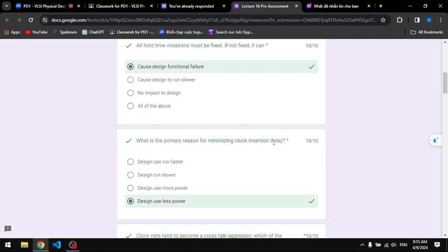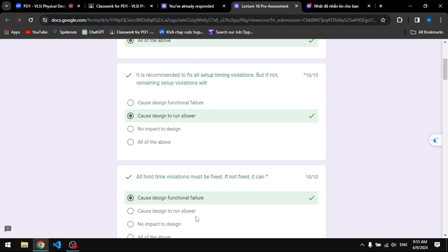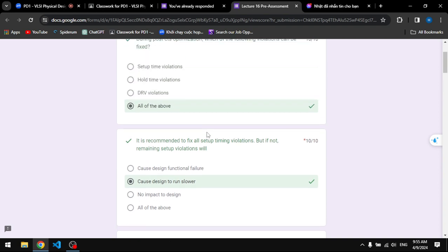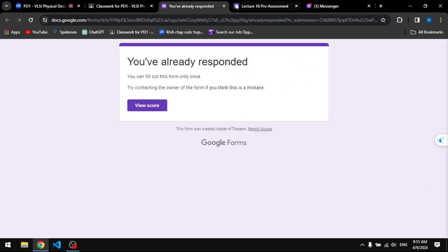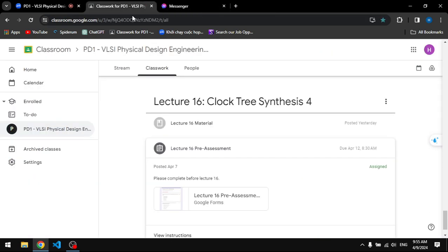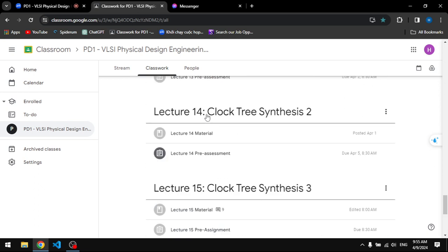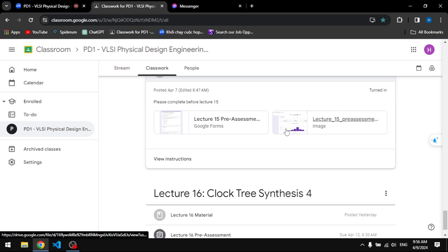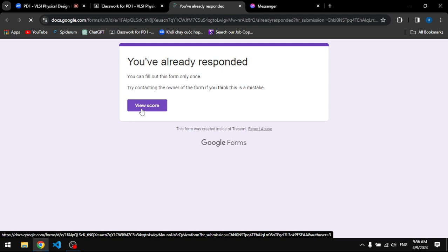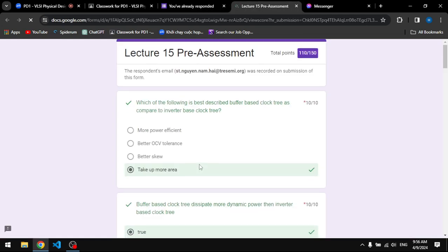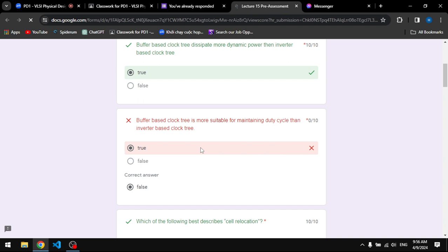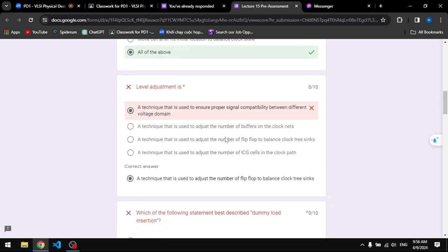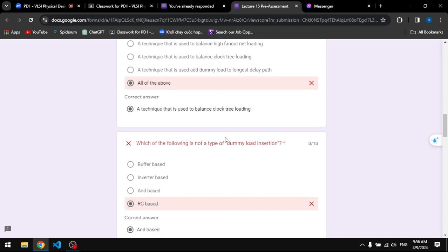Okay, let's do one more: load splitting. I don't think we have talked about load splitting. Splitting in English means dividing something in half, or in thirds or fourths. So basically, chop it in half. It's a process of inserting buffers to split the fanouts and resize the current drive to meet CTS or DRV constraints. So this technique is used in CTS and also in DRVs.